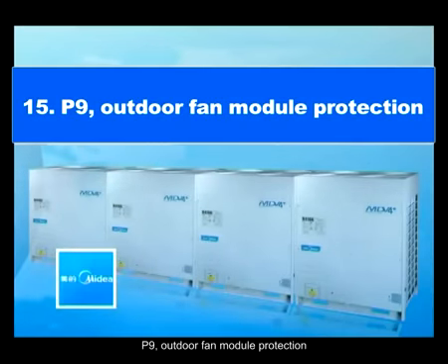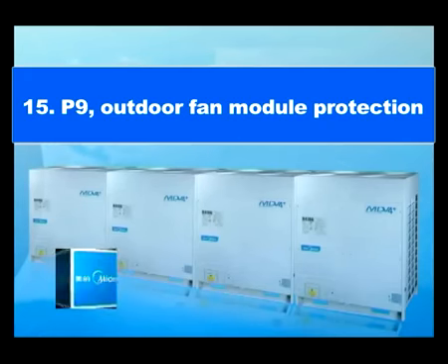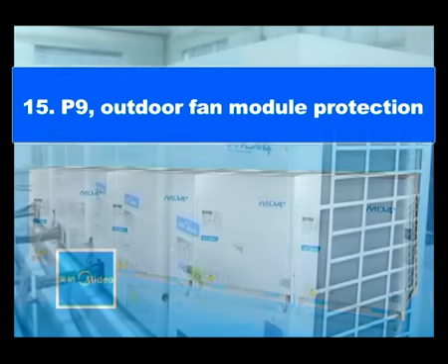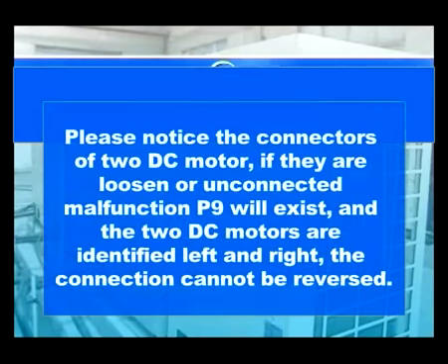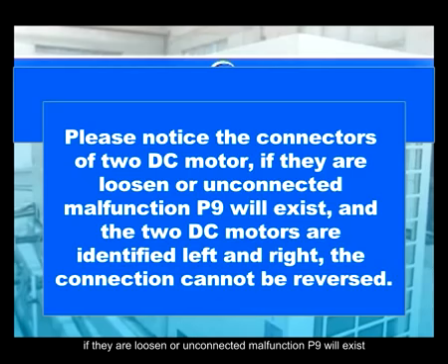P9. Outdoor fan module protection. Please note the connectors of the 2 DC motors. If they are loosened or unconnected, a malfunction will occur and P9 will appear. The 2 DC motors are identified as left and right. The connection cannot be reversed.